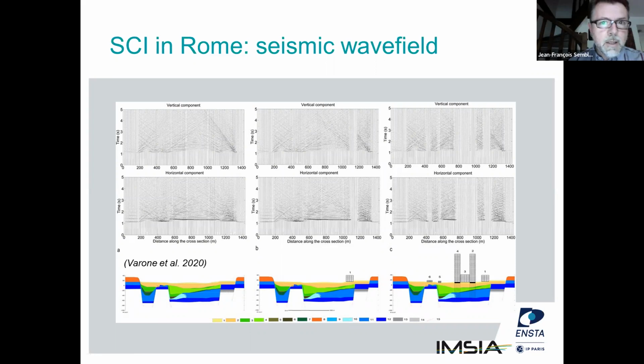Yeah, in fact, we have various effects. Depending on the building features, we may have some kinematic effect at the interface, but mainly for body waves. We may have some inertial effects, but it depends also on, for instance, the rocking of the structure. And we may also have some interactions due to surface wave propagation and generation.